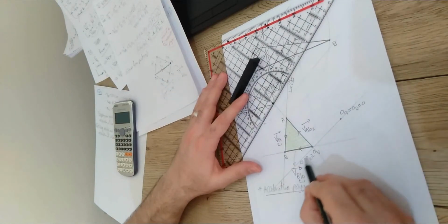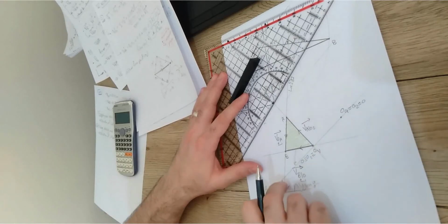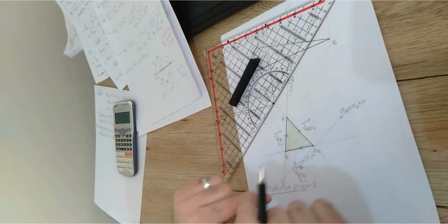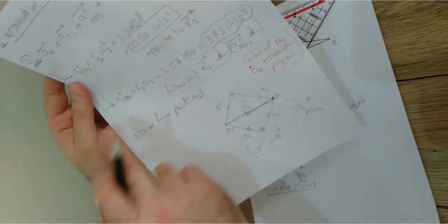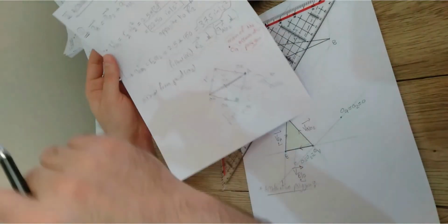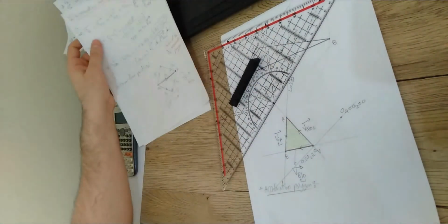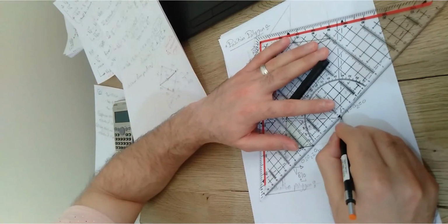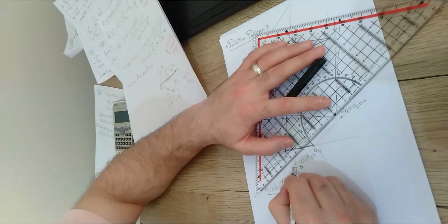So over this line, I should measure 90 millimeter, and the end of this line is going to give me the normal only. The end of this line, will it not give us the point A? No, we still have the tangential. Then after the tangential, at the end of the tangential, we're going to find the point A. So I'm going to measure 90 from this point. 90 should be up to here. This is the point here.